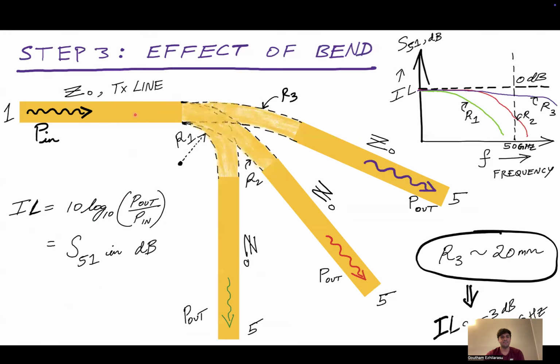And so how did I design this RF link? I kind of split it into several individual designs that I put together. First I started with designing just the 50 ohm impedance transmission line at the SMA side and the pad side. Then I designed a linear taper, a straight taper. Then I looked at the effects of bends, and then I combined everything together to create a fan-in that has both a taper along with a bend.